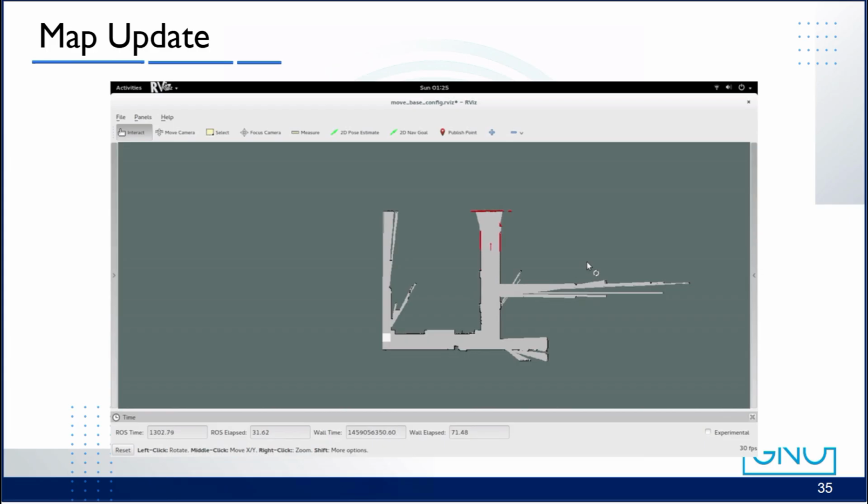Once the change in pose is estimated, each laser scan is transformed into the global frame and used to update the global map. But an occupancy grid does not immediately label a cell as a wall or free space based on a single scan. Doing so would introduce significant noise because each measurement carries uncertainty. If you look closely, the algorithm internally keeps a numerical value for every cell, not just the binary occupied or free state we see visually.